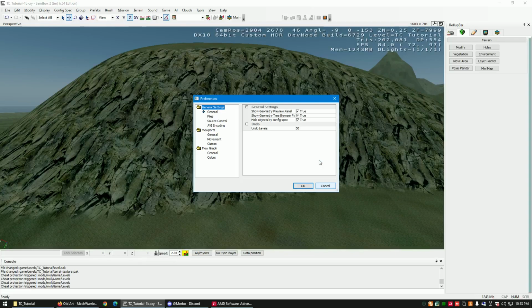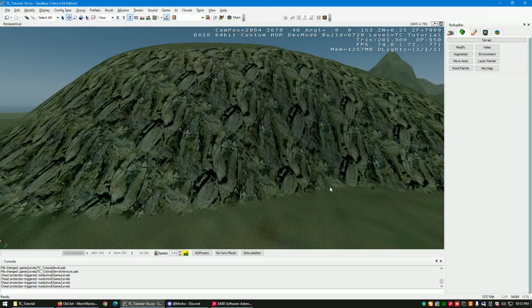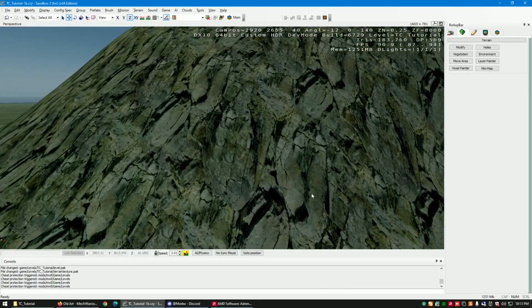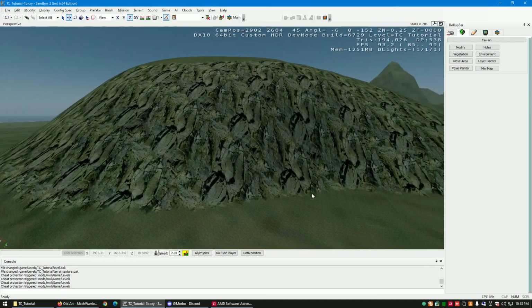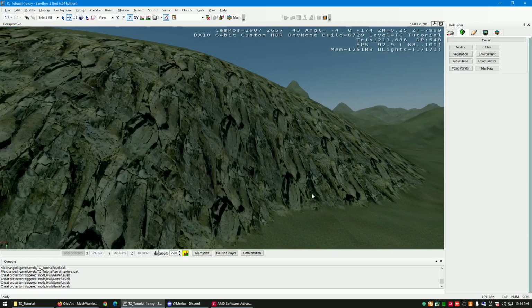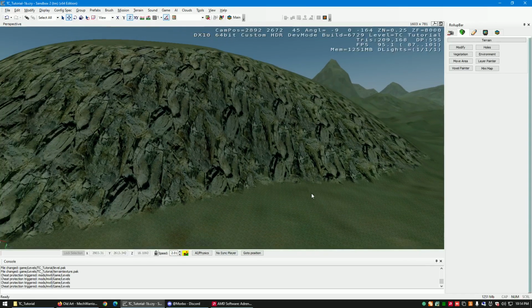The more undo levels you have, the more memory it will take up, and it'll take them up relatively quickly. If you have like 8 gigs of memory and you don't have anything else running, you'll be fine. You can run at 50, I find, without any issues. And I've run the editor on a 4 gig machine. It's a little bit more clunky, slower, and it does crash a little bit more, but if you have 8 gigs of memory, then I think you'll be fine with 50. But if you do see a bunch of crashing, like you mentioned you had a few, bring it down to 20 or so and see what happens.